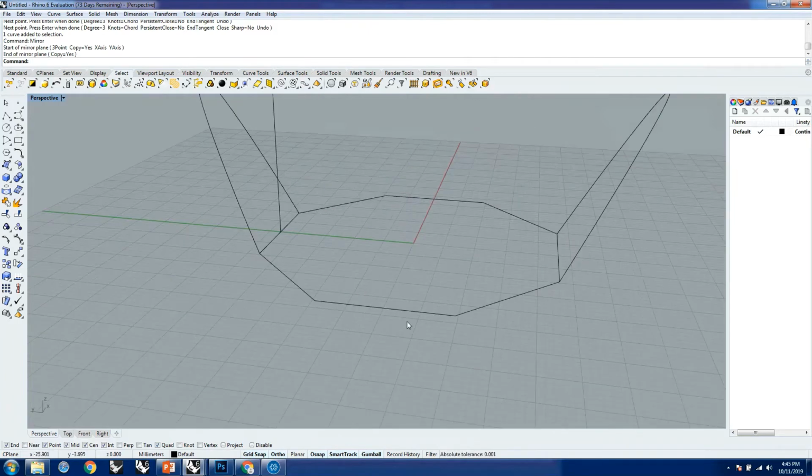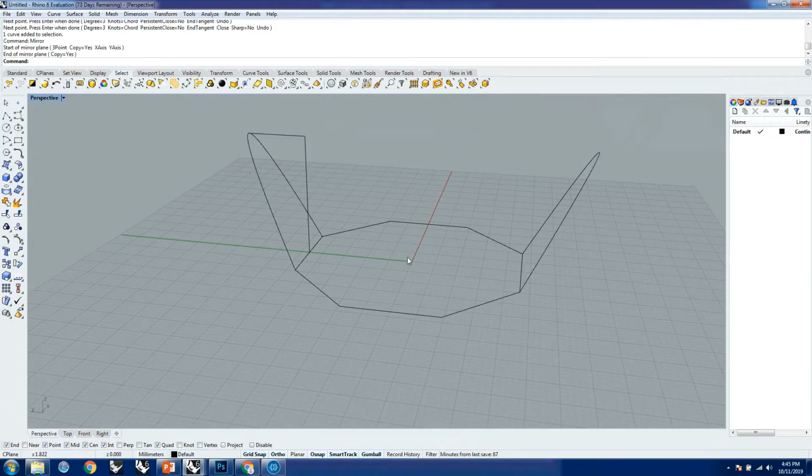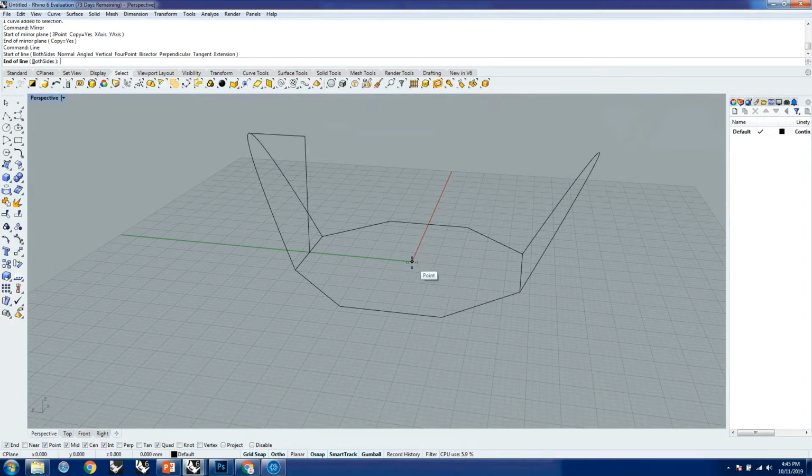Second, I'm going to make a point somewhere here that is at a certain height, let's say 12.5, the half of what we have been using for now. So I'm going to start with the origin. I'm pressing Control, clicking on it so that we can draft in the Z-axis. And I'm going to type 12.5.